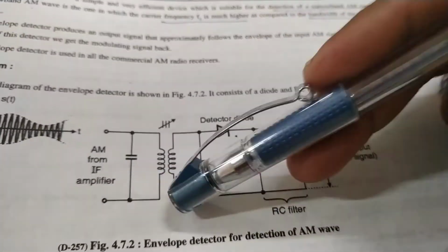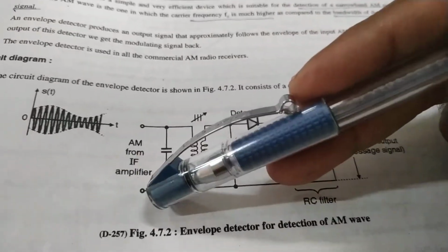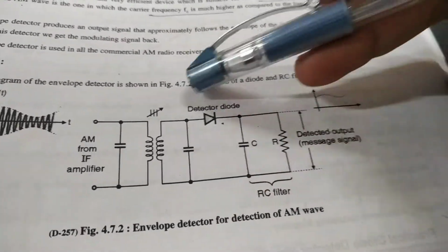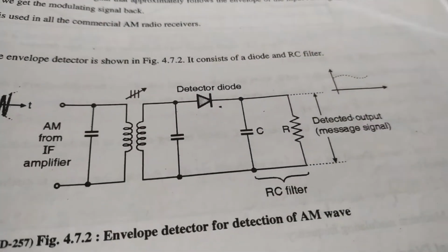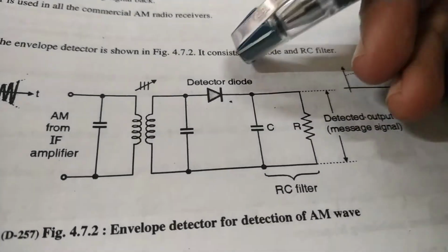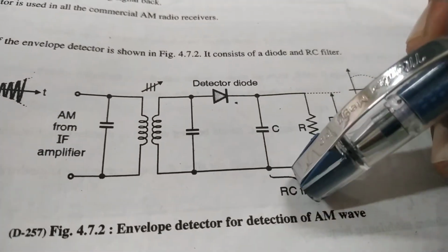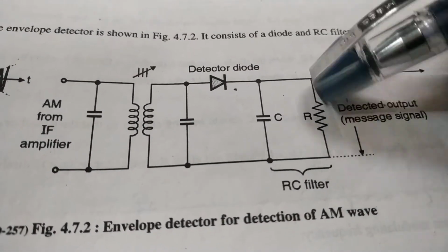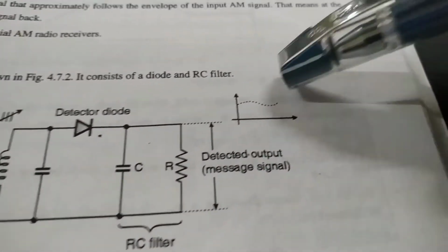The signal that will be coming across this transformer is the amplitude modulated signal. This signal is transferred to the diode. It comes across the diode, and the diode comes into the forward bias condition. When it comes into forward bias, the capacitor starts charging. The capacitor charges up to the peak value. When the capacitor is fully charged, the diode goes into reverse bias. The point at which the diode turns off, the capacitor starts discharging, and whenever the capacitor discharges through this resistor, the discharging period of the capacitor is generated, that is, it recovers the original